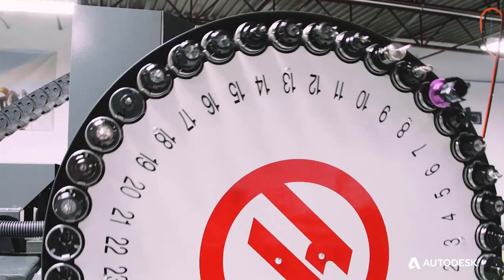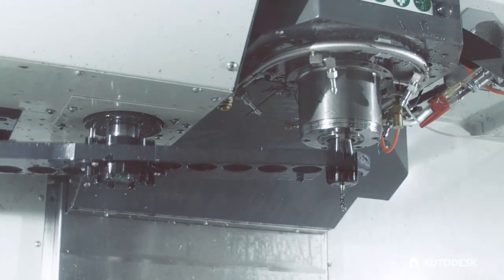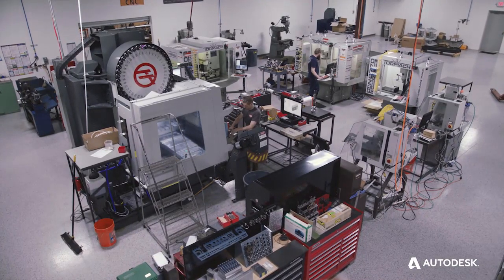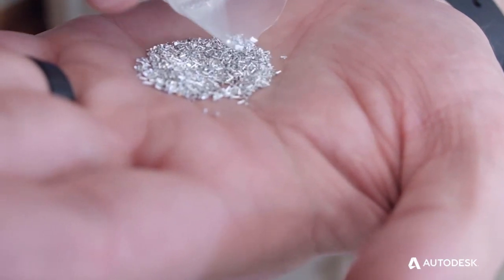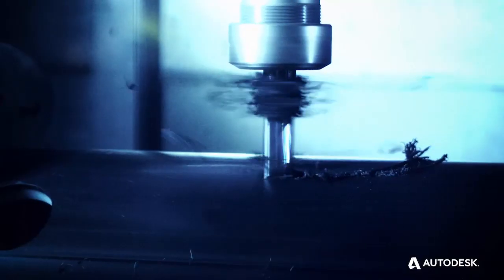This is important for production shops, where saving seconds per part, multiplied by the hundreds or thousands of parts produced, can make a significant impact on productivity and ability to meet production deadlines. Keeping the tool load constant and spreading the wear across the entire flute length also improves process reliability and reduces tool breakage. Every tool break means a tool replacement, which can take several minutes, a significant process in a production environment where seconds count. Constant engagement strategies enable machinists at all levels to push their machines faster, increase productivity, and improve process reliability, from prototyping to high production environments.